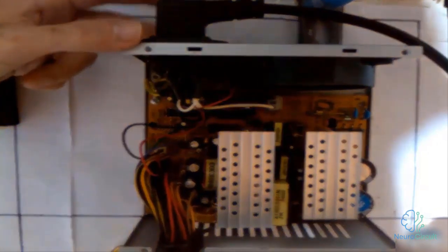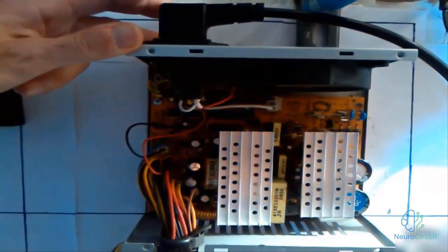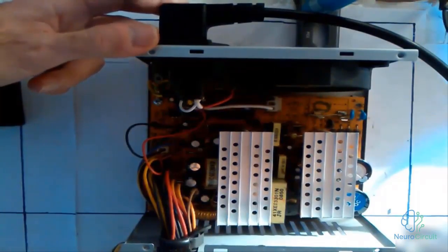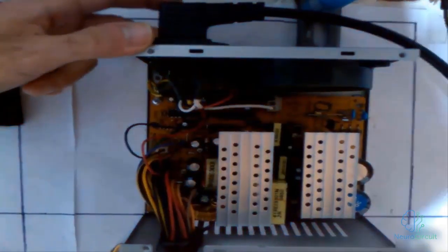Alright, now when I press the power switch, you'll see a yellow light appear. This yellow light here is from the test lamp. That means if I plug this power supply directly into the electricity, it will trip the circuit breaker and might even damage the power supply itself. Here it could cause a short circuit and burn out, which is why it's always recommended to use a test lamp. Let me show you again.